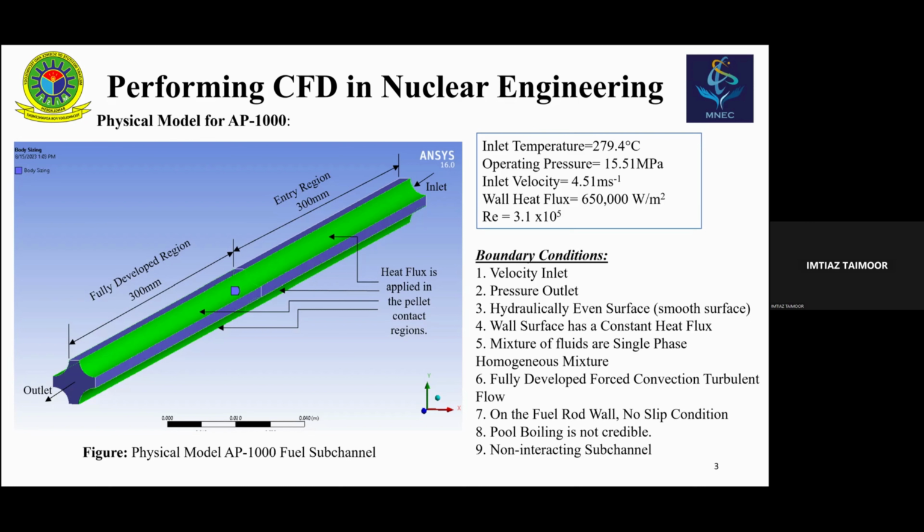That is the conservation of momentum equation, which is the famous Navier-Stokes equation. And then we saw the partial differential equation for the conservation of energy. So let's have a clear picture of why, whenever you are doing the simulation of a computational fluid domain, we have considered these three equations. One is the conservation or continuity equation.